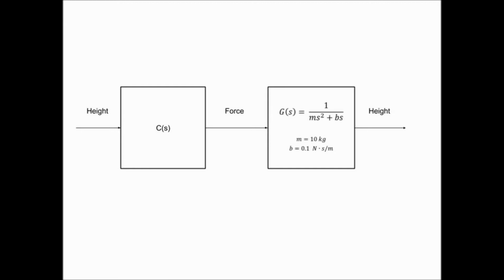To model the plant of our system, the quadcopter itself, we used simple physics concepts. We selected the mass of our drone and payload to be 10 kilograms. This was founded on the prototype Amazon drones, and you can find a citation in the report. We selected the damping coefficient to be non-zero, but still much smaller than the mass, so that the system behaved significantly underdamped, just like the real world.